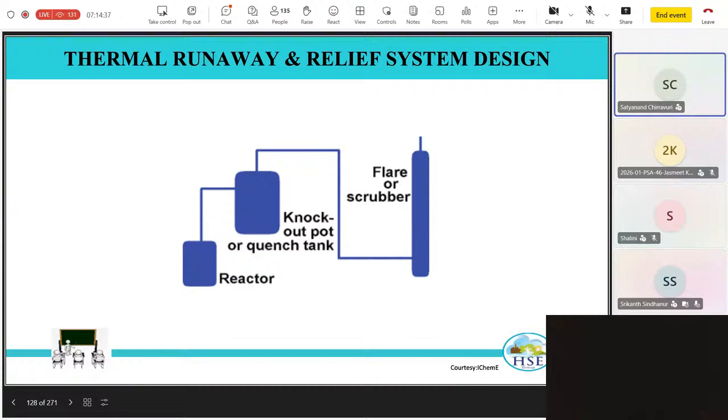And then finally look into the adiabatic calorimeter for all these critical reactions. Do adiabatic calorimetry studies also, get the data, and manage your bad or potentially disastrous situations by designing proper relief systems and vents, so that your organization doesn't get into problems.